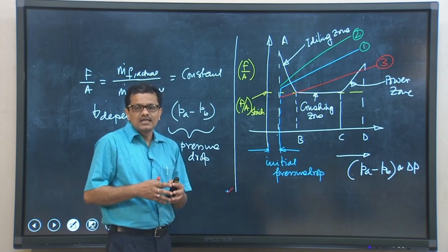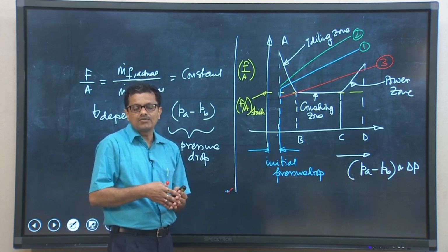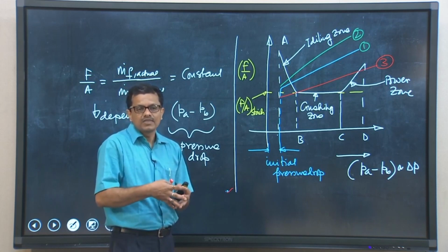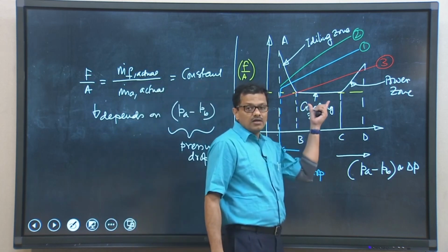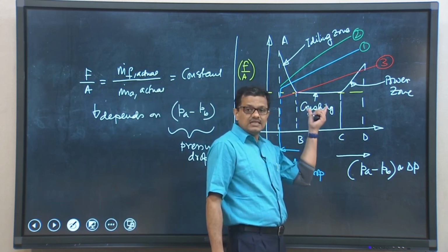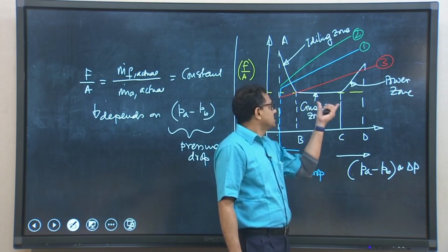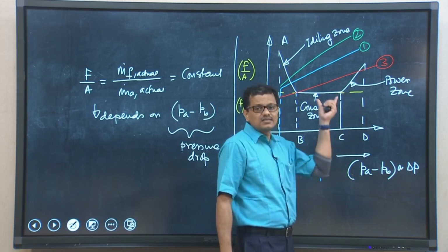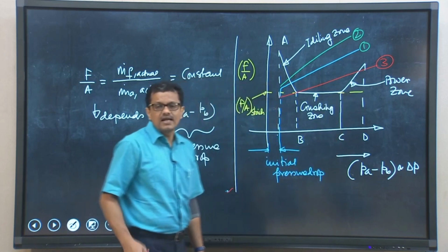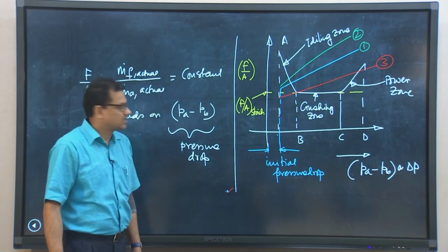So, what we can see is that there are a few limitations with the simple float type carburetor, because the simple float type carburetor cannot supply fuel air ratio as needed by the engine during its operation in 3 different zones. So, this is what is very important, and I can say these are the drawbacks of the simple float type carburetor.